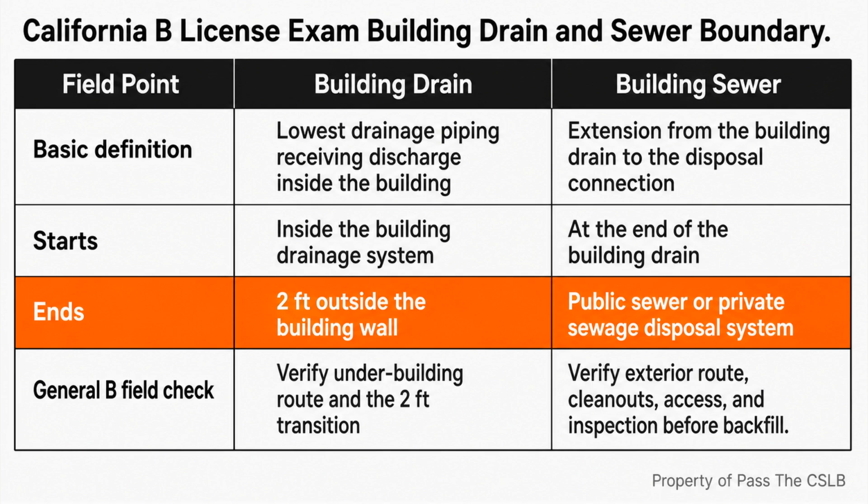If one of those three is missed, the problem usually returns as a failed inspection, excavation, demolition, or a drainage defect. The central idea is that a gravity drainage line is not just pipe placed in a trench. Its performance depends on the relationship between elevation, direction, access, and the work that will later conceal it. A general building contractor does not take over plumbing design or drainage fixture unit sizing. I stay on the supervision side of the line. I coordinate the approved layout, verify visible field conditions, keep the work safe, and stop concealment when a required condition is missing.